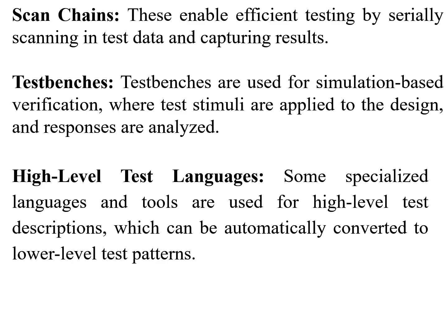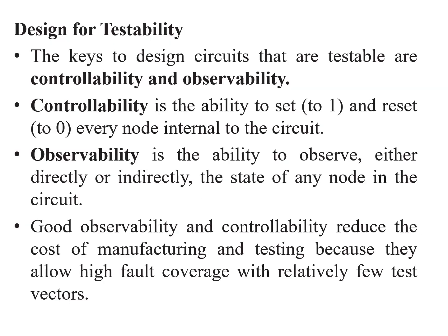Scan chains. These enable efficient testing by serially scanning in test data and capturing results. Test benches. Test benches are used for simulation-based verification where test stimuli are applied to the design and responses are analyzed. High-level test languages. Some specialized languages and tools are used for high-level test descriptions, which can be automatically converted to lower-level test patterns. Design for testability.